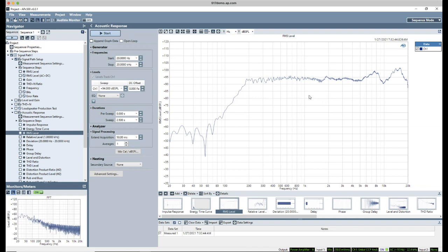Now, as I'll demonstrate in a moment, I could potentially use this as is. By having a reference microphone, I could, in some sense, divide out the response of the speaker. But what I'm going to do is equalize my speaker. Now, when I equalize my speaker, I've got to be aware of the fact that I can't boost the output of the speaker at 20 hertz enough to get to SPL. I can generally equalize the speaker over some reasonable range of output. So let me show you what that looks like.